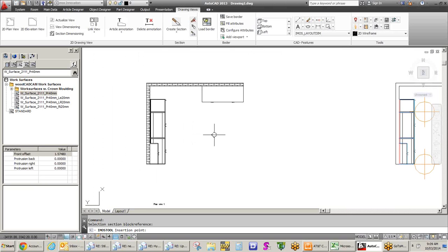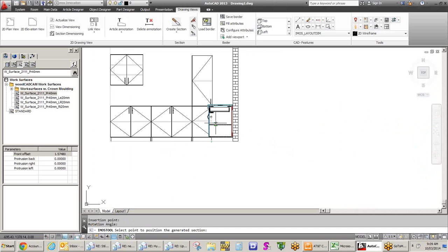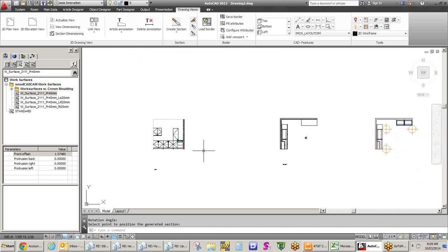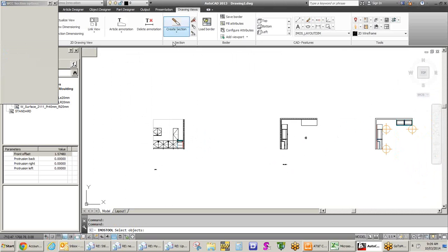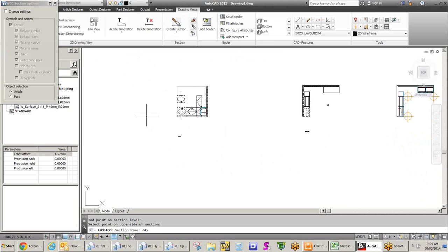I'm going to back off where I'm cutting this section or making the elevation of this, so it's going to be looking at the return of that other cabinet. It's wherever you have that pointed as to where it's going to do the slice for it. So now we'll see that I'm actually getting in my drawing what I want. As you know, because I believe you do have some Microvellum experience, when you wanted to do things like cross sections and that kind of stuff, it was very much limited to the 2D draw tokens within the CutX file. Here I have a free-form ability to where I can cut it wherever I want, and I can look at it on either side of the line, and so that works out good.